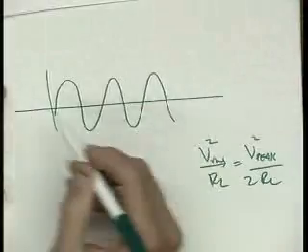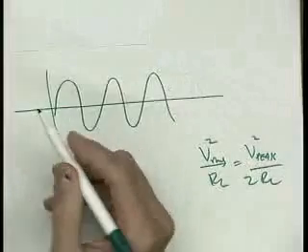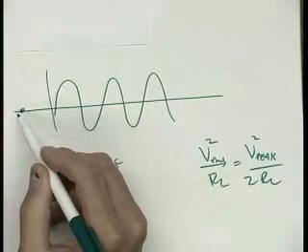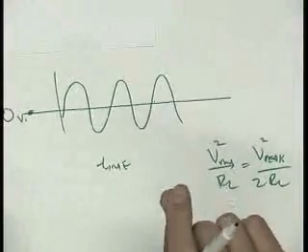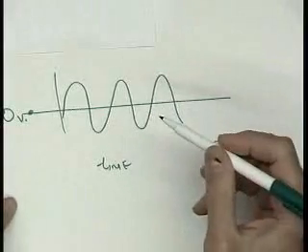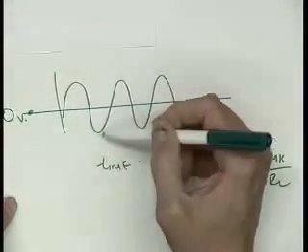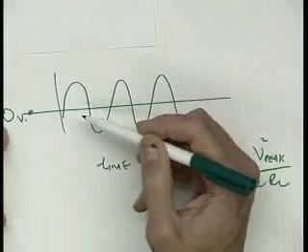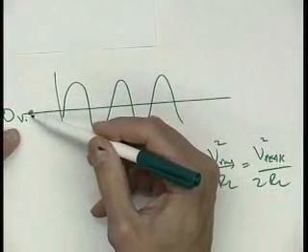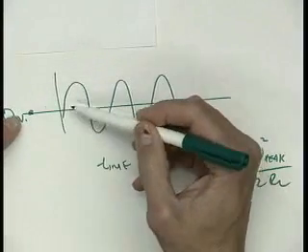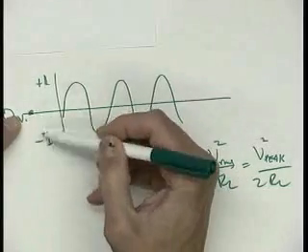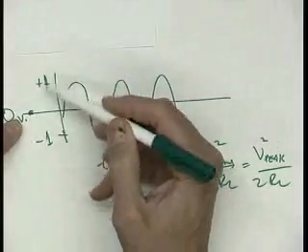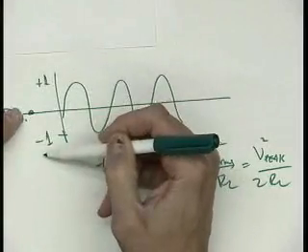And so assume we're in a sine wave, and choose your own value of DC level. I think for the input, what that was all about was so that the output would be around 0 volts. What we always assume is that the output needs to be symmetrical around 0 volts, okay? So what they're saying is that you assume that you can set the input so the output's at 0 volts, and it'll swing to +1 and -1. And you can choose whatever value of input voltage to make sure that you're symmetrical, at 0 and plus or minus 1. So that's what it's all about.